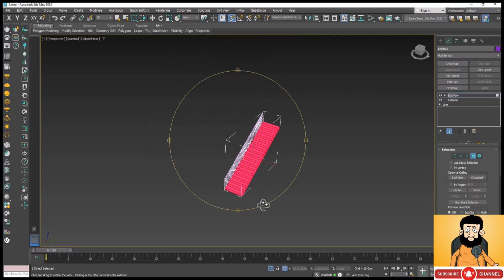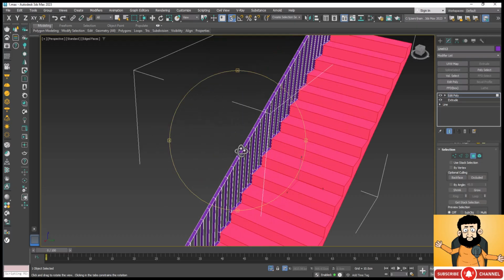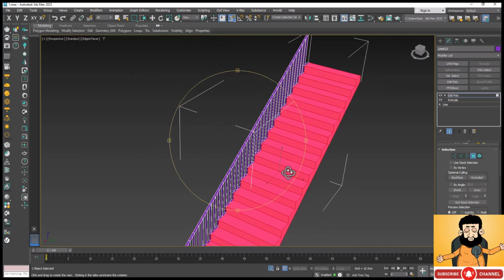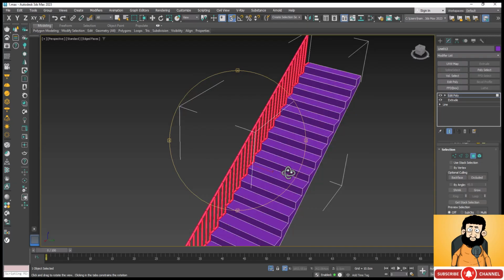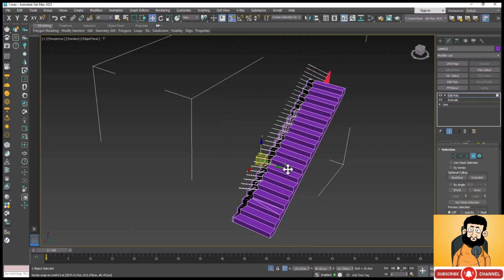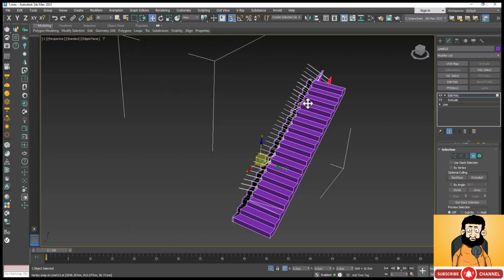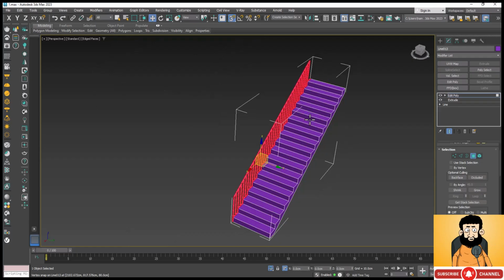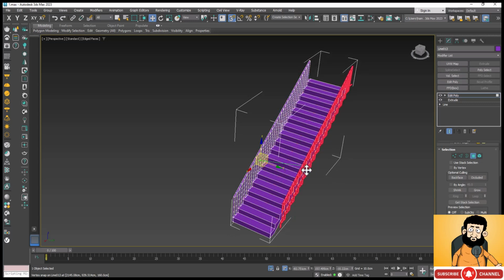These are selected. Now I'm going to press Ctrl I. When you press Ctrl I, your selection will be inverted, meaning that the place you didn't select will be selected. Now we're going to go. It's the same again. I just held down Shift and wanted to copy. It can't. I'm going to press Ctrl Z. For this, we have to hold down Ctrl Shift to copy it.